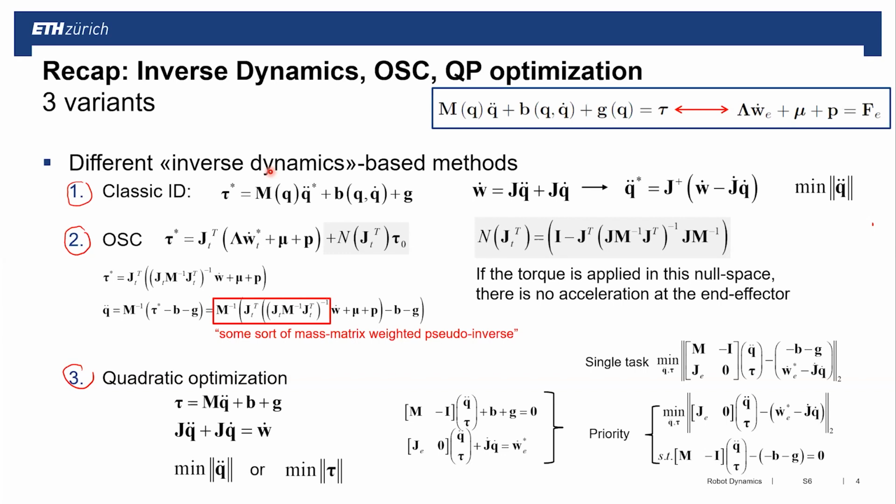But as soon as you have redundancy, or as soon as you can't follow it exactly, the optimization that happens in the second or in the first solution is different. We analyzed this, looking at what kind of null space projection matrices we have here. This will also be seen in the next video segment, as it is the exact same null space projection matrix that we will revisit in the floating base systems, and in collisions of robotic systems.